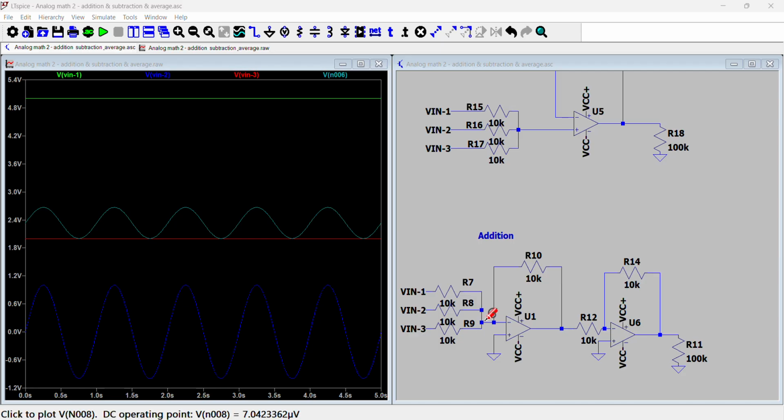And then what actually happens now is you have a Kirchhoff's current law around this point where the voltage drops across all three of these inputs has to add up to the same voltage drop across here, because the current has to be conserved around this point. So current entering equals the current exiting. And because of that, you have a summing effect on the voltages. And at this point, the voltage is actually the negative of the sum of all three of these voltages. So I'll just demonstrate that.